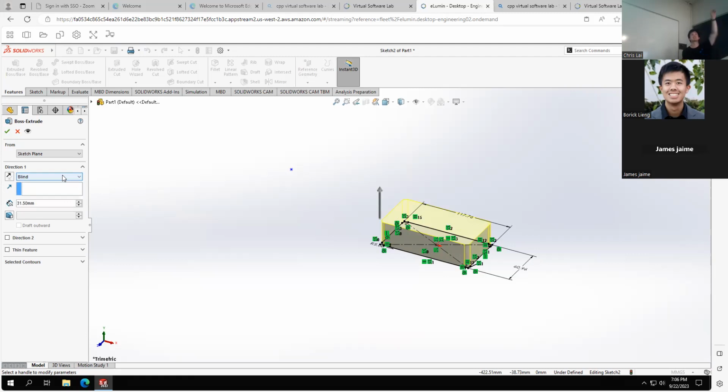For the extrude feature, you have different options of how you can extrude it, right? You could double click the sketch in the feature tree. That lets you go back into it. And then you can click on the Features tab afterwards. Yeah. Is it good? Yeah.